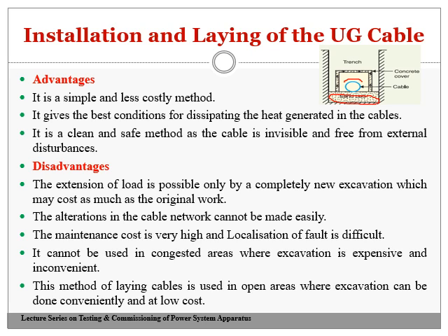It cannot be used in congested areas where excavation is expensive and inconvenient. In some cases, especially in cities, everywhere there will be an underground drainage system, waterworks, or pipelines. It becomes very difficult in congested areas, as excavation for the underground cable becomes an expensive and inconvenient method. This method of laying cable is feasible in open areas.